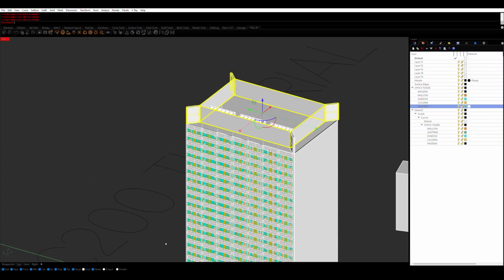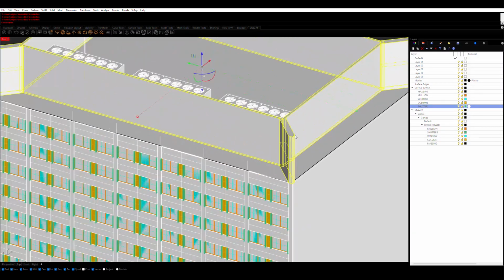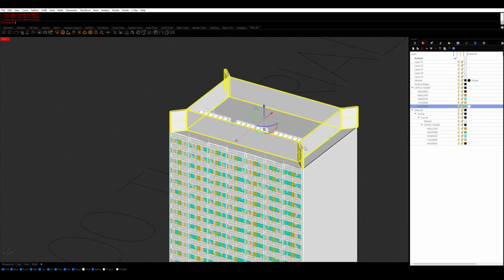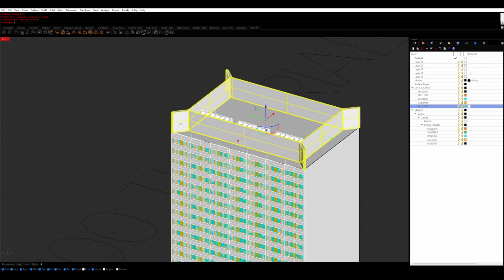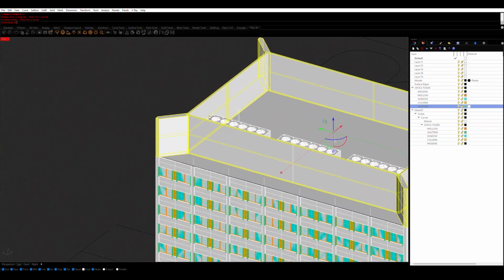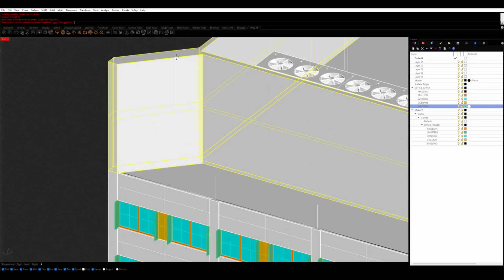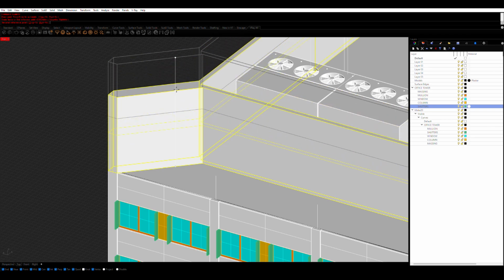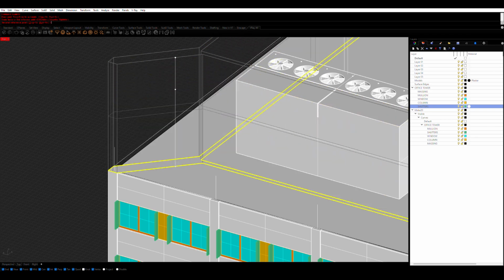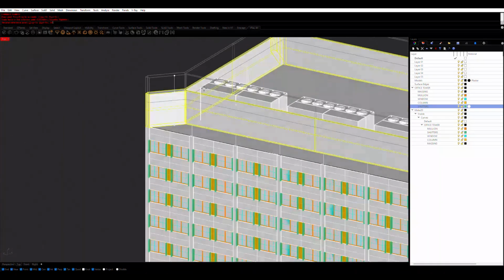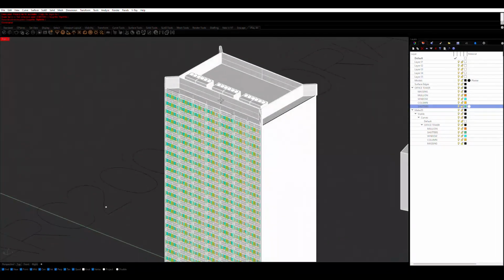It also seems like our bounding wall might be a bit too large. So we'll do a Boolean union, again merging all the faces. And we can bring this down maybe, let's say 16 feet.